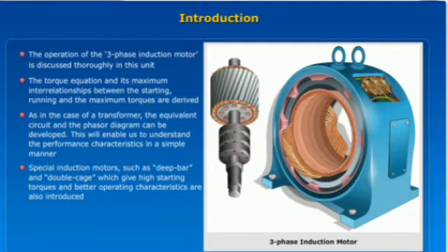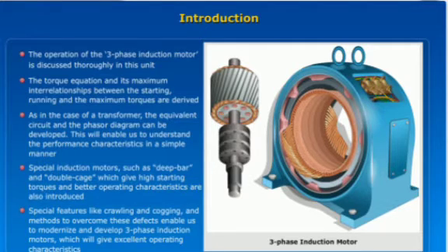Special induction motors such as deep bar and double cage, which give high starting torques and better operating characteristics, are also introduced. Special features like crawling and cogging, and methods to overcome these defects, enable us to modernize and develop three-phase induction motors, which will give excellent operating characteristics.